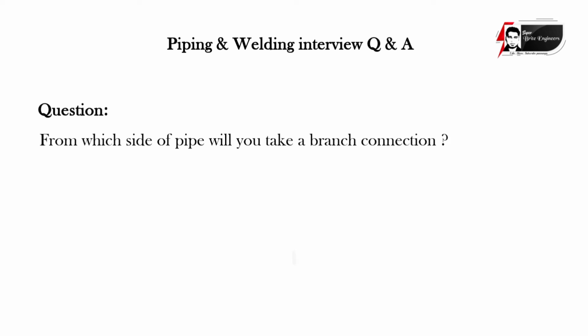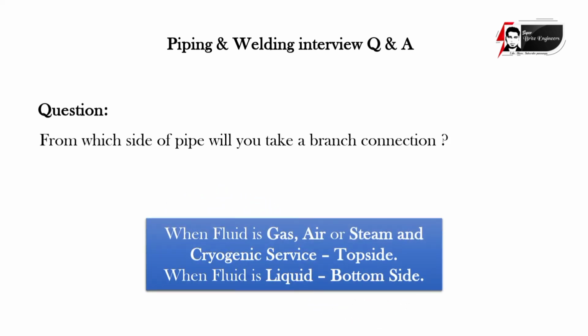From which side of the pipe will you take the branch connections? When the fluid is gas, air, steam and cryogenic service, from the top side. When the fluid is a liquid, from the bottom side.